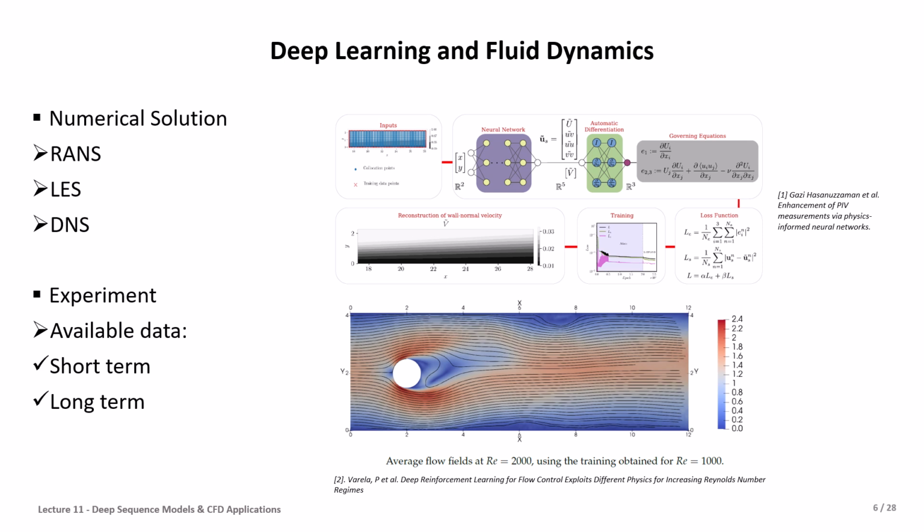Therefore, we will present the sequential model, which basically works for time series, and we will explain how it can be connected to the physics of the problem with turbulent flow, and we will present one of the recent novel applications of deep learning in turbulent flow from our research group.